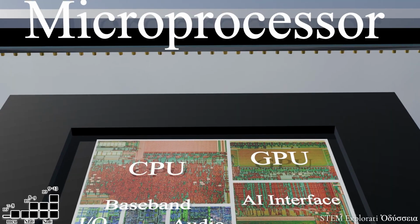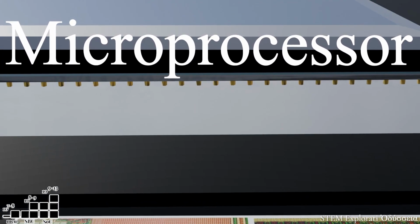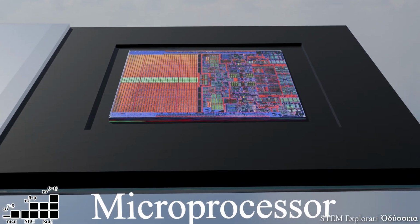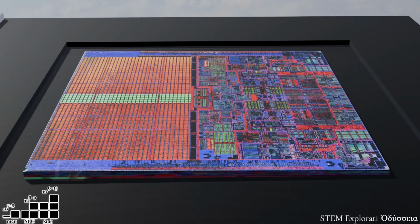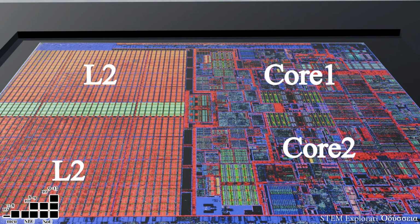And at the next level, we have modern microprocessors, or CPUs. Observe how a significant portion of the die is taken up by on-chip cache memory, like the large L2 caches you see here on the left-hand side, pushing transistor counts into the billions. Also note that the above processor has two independent cores, further speeding up calculations. Thus, from a few thousand transistors in the earliest microcontrollers to billions in today's chips, it's an incredible leap in complexity, powering everything from microcontrollers to data centers.